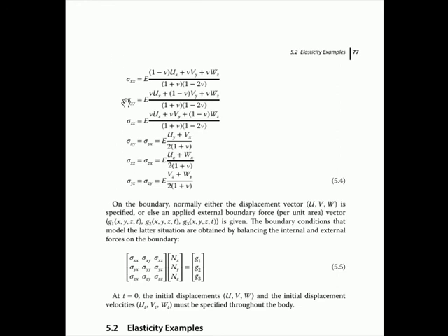We get these equations. So basically you can plug this in for sigma xx. Remember that xx is not derivatives, that's just part of the notation. So sigma xx is that, sigma yy, and so forth. Plug these into those equations I just showed you. And remember, we have first derivatives of the stresses, and the stresses are functions of the first derivatives of the displacements. So you get second derivatives of the displacements in that equation.